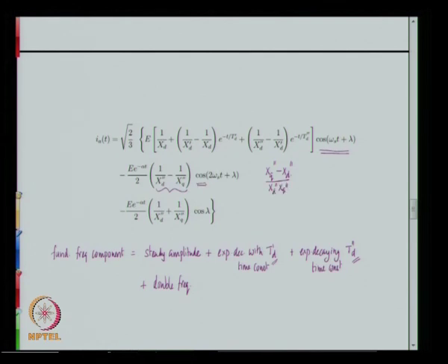So the amplitude of the double frequency component, second harmonic, will really depend upon the difference of the subtransient reactances along the direct and quadrature axis. Normally this value is pretty small, the subtransient reactances themselves are small, and this further is the difference of these two which is very small, and therefore the double frequency component is normally expected to be really small in amplitude and may not show up in the actual waveform of Ia of t.